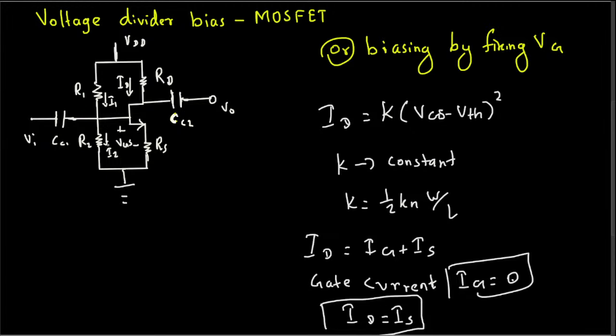Now if I just take the input part of it, the input part is whatever is inside right here, and here we have the R1 resistance, the R2 resistance, and a voltage source, and the voltage in between is the gate voltage, and that is connected to the ground at the bottom. So here if I do that, this is going to be R1 right here, and this is R2, and here we have the gate, and this is the voltage source.